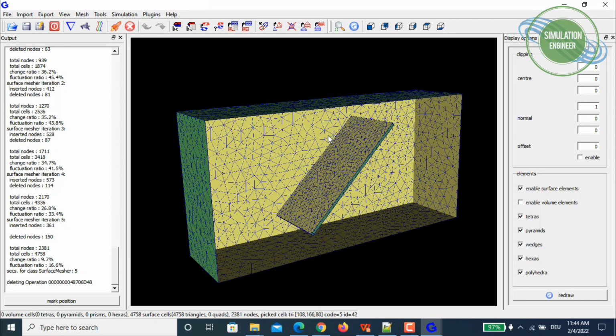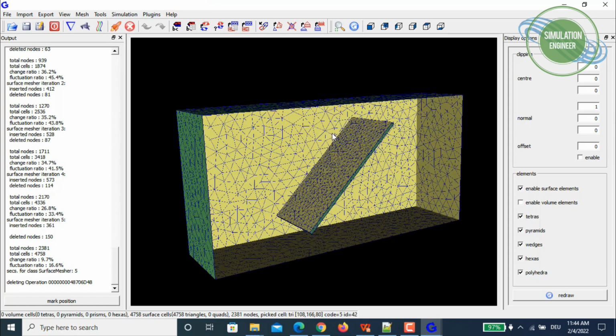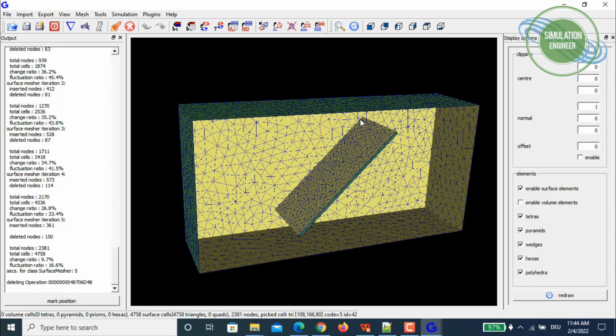Now we will be using edge features or edge refinement. So we will say the damper top part and the damper back part, similarly the right part and the damper. All these edges will be accessed with the combination of damper surface patches to really define a surface mesh refinement. I will show you how we can perform this.